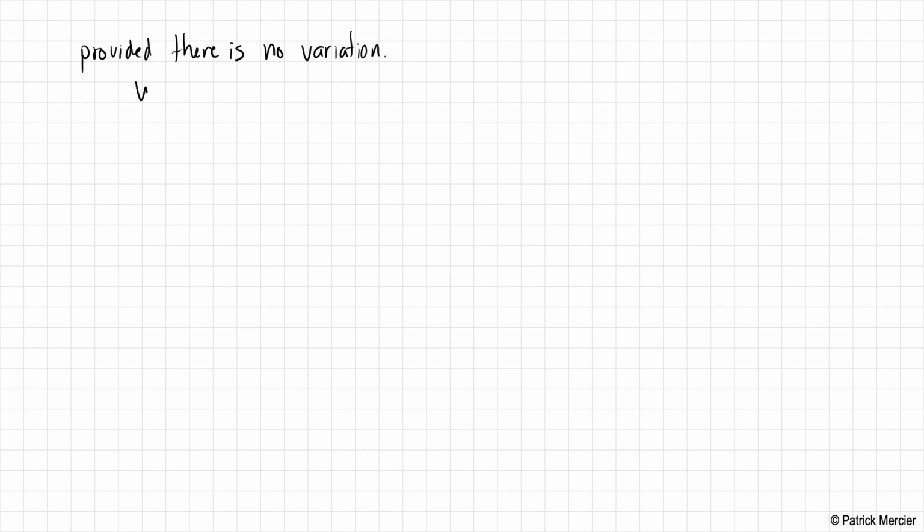Okay, so given that, we can say that CGS,total is equal to CGS plus CGS,overlap. And you'll notice I'm being a little sloppy in the use of uppercase versus lowercase variables here. In analog design, this means something. In digital design, we can get away with being a little bit more sloppy, although I will try and stay a little bit more consistent.